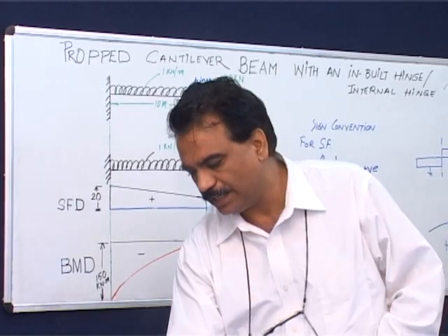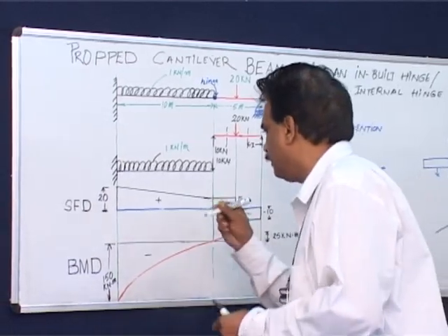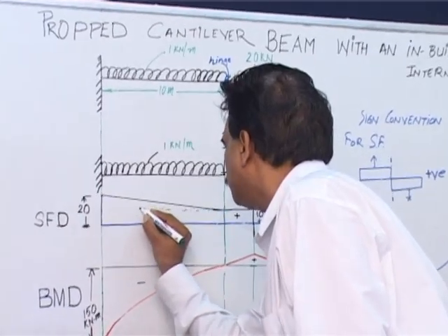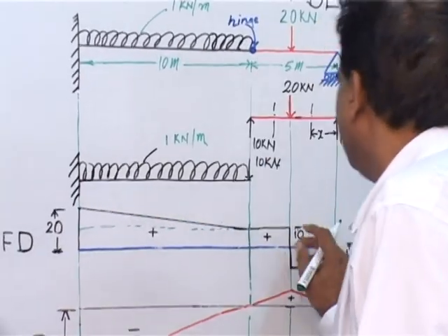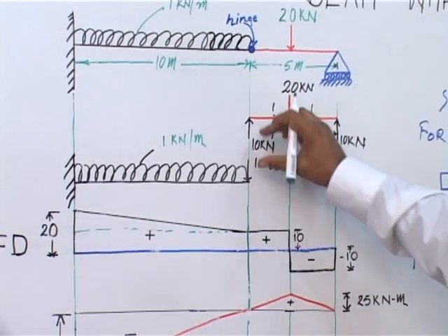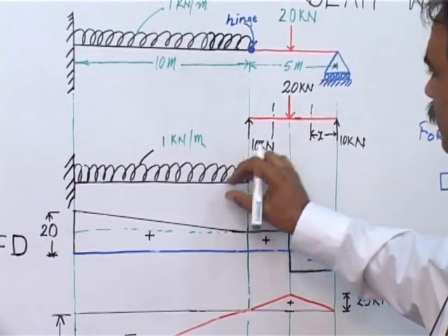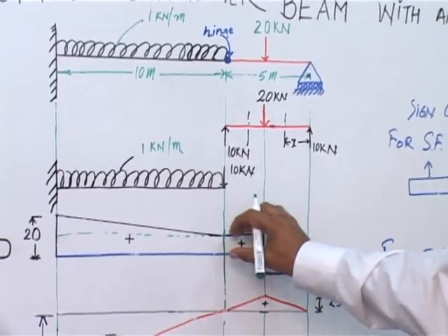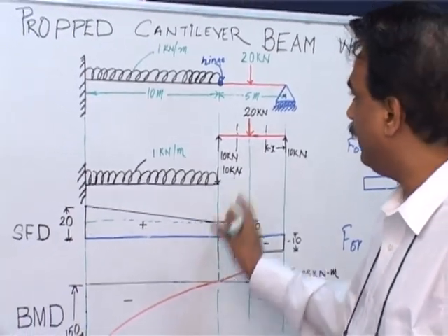So in this case, the cantilever portion, this is what I was saying, this portion coming from here is a continuous rectangle effect of this load here, and thereafter the UDL triangle. In total you have a trapezoidal shear force diagram to the left of this hinge.